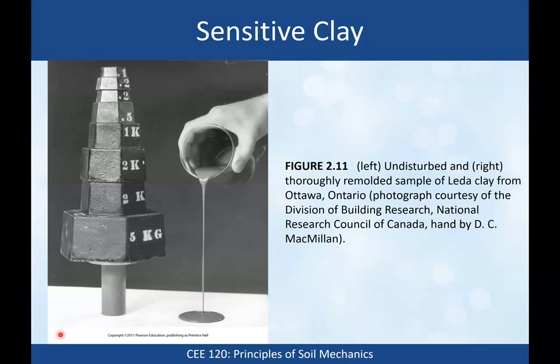And what's happening here is that the electrochemical interactions of the clay are highly influenced by cations in the water. So if a clay is deposited in the ocean as a marine clay deposit, the sodium from the seawater will be attracted to the negative surface of the clay mineral, and that will allow the clay minerals to come closer together.